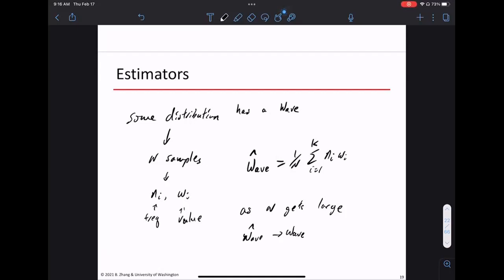In practice, we don't do it that way because we care about high wind speed much more than we care about low wind speed. So in practice, when you try to develop a wind turbine, first you do a couple measurements, figure out when typically high wind and low wind is. They disregard the low wind possibilities, you don't care. I don't need a very accurate estimate of low speed wind. I don't generate power that way. You figure out what are the possible high speed times, then you measure those very accurately. Take a lot of measurements there. So doing this in practice, there's a lot of art to this.